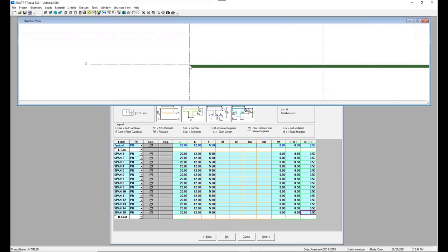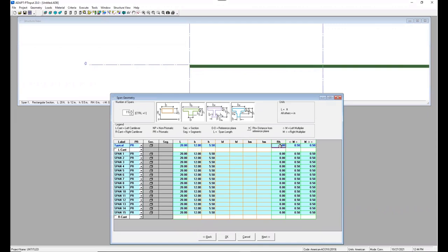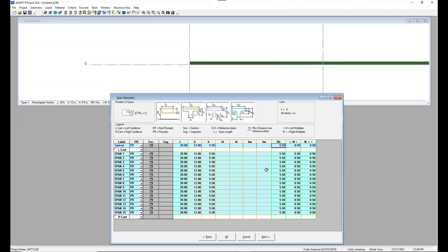And right now with our datum being at the top of the slab, all of our CGS values are going to be negative, which really doesn't make sense. So what we often recommend is typing in your actual slab thickness or beam depth in this field. And you'll notice it bumped that datum down to the bottom. And now all of our tendon heights will be referenced from this datum with a positive number.